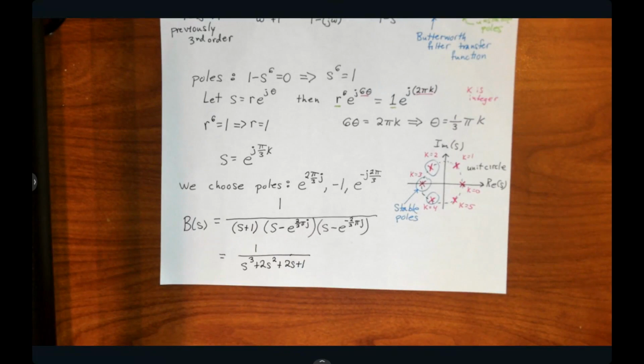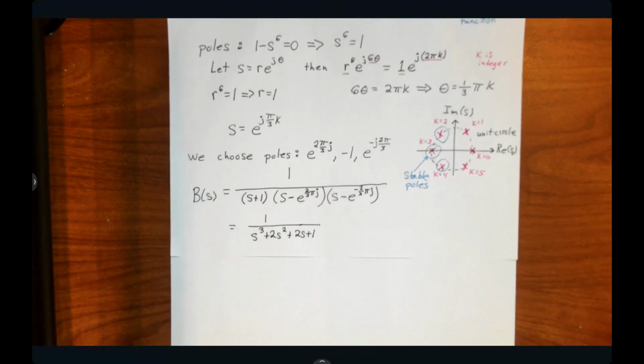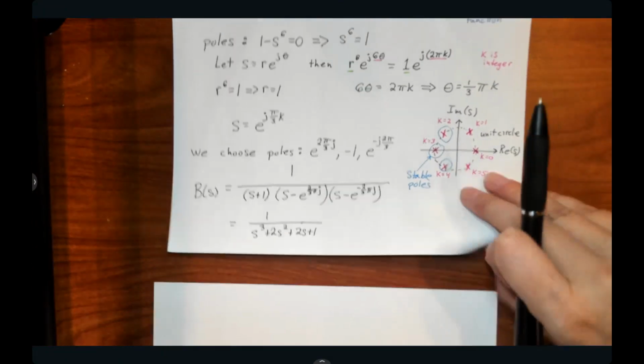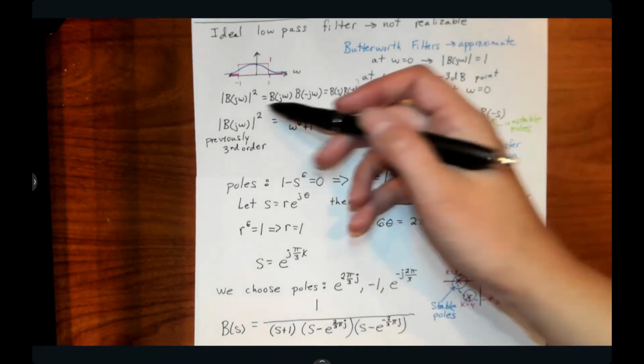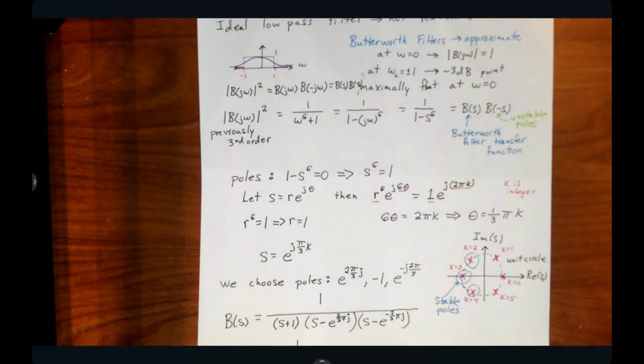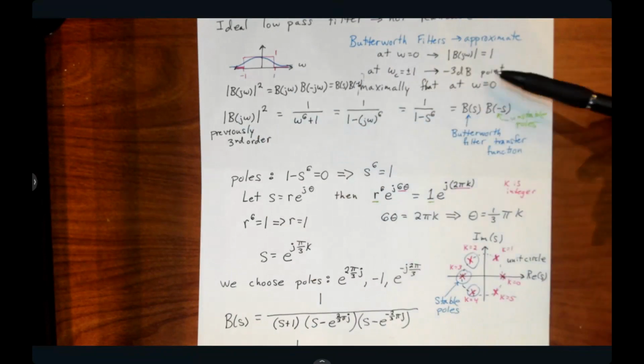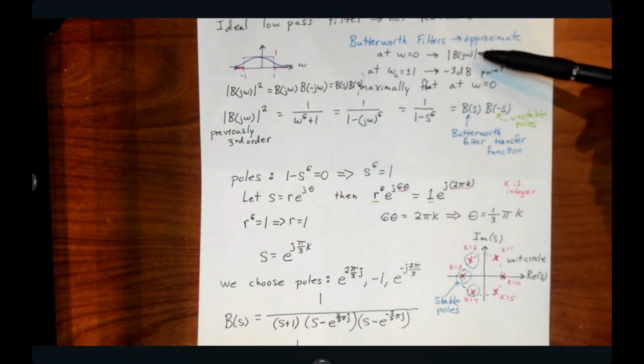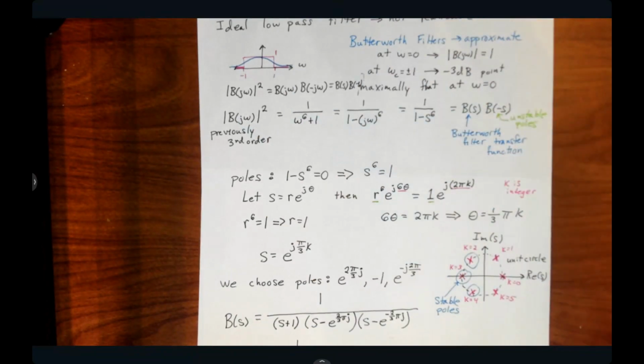All right, so all this derivation we did for a specific order that we wanted. We started off with this idea that we wanted something which was a cubic in the denominator, so a third order transfer function. And then from there, we formed this idea of the magnitude of the response, and we used that magnitude to figure out all the constraints that I want. What form am I going to end up with?